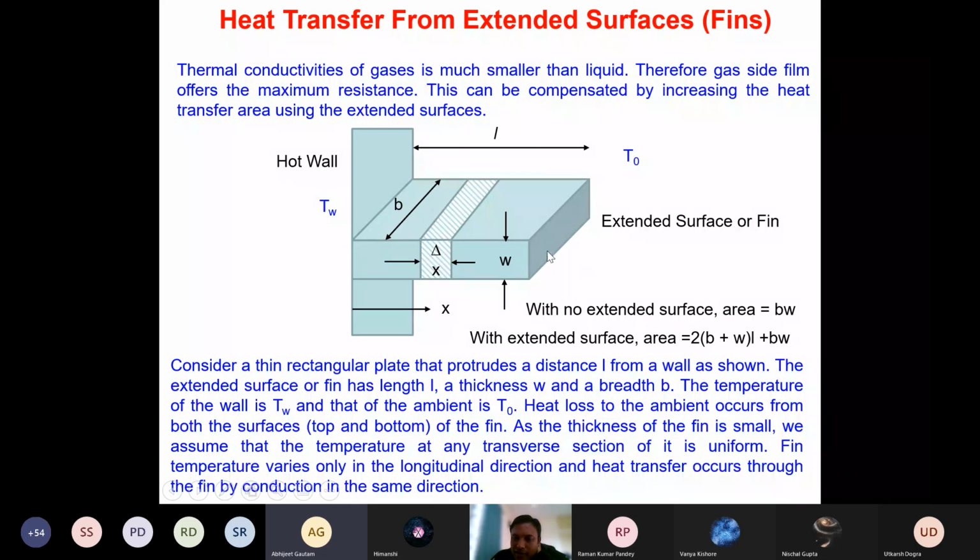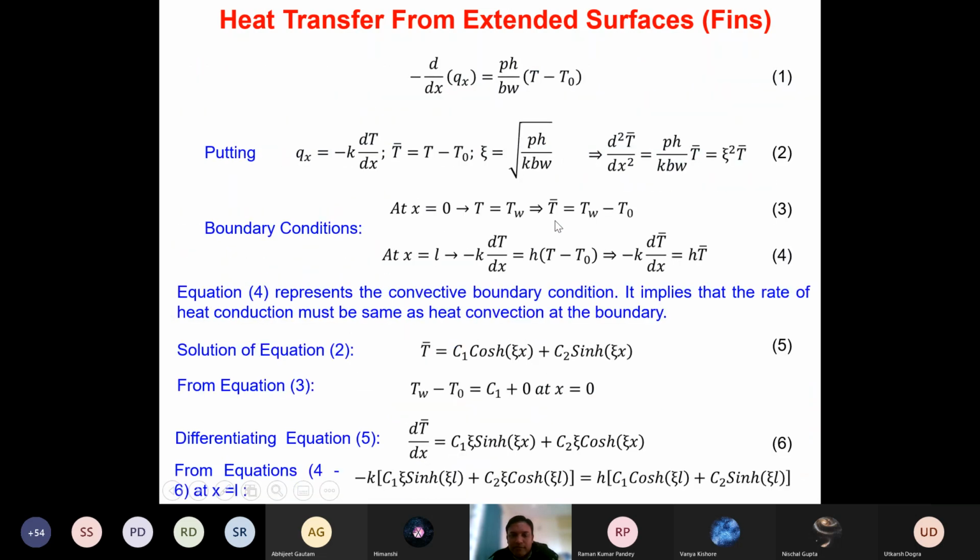Convection we have taken. So that's why the maximum we have calculated is based on this. When we are calculating the theoretical maximum, even then, in the other case, this surface is not contributing in the heat transfer at all. Because what we are assuming in the simplified case is that by the time I reach this end, my temperature is already becoming T naught. So that means this area is not at all contributing in the convective heat transfer. Do you all agree?